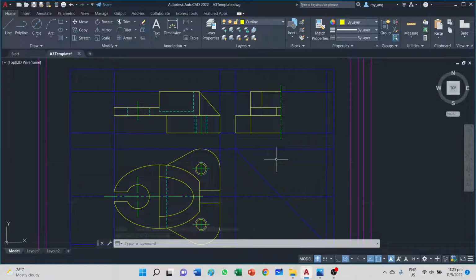Okay, now at this point of time you would want to consider drawing your hidden lines. You need to check through your drawing and ask yourself if you have gotten all the outlines ready, right? And once you have the bulk of it, then you approach the hidden lines.